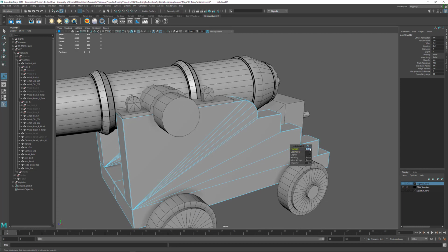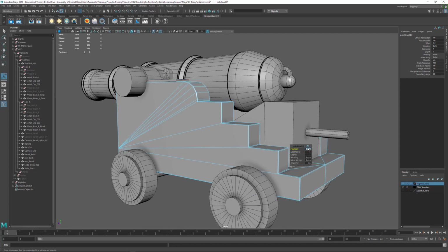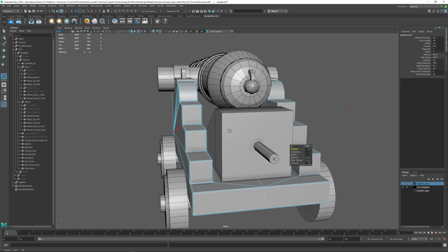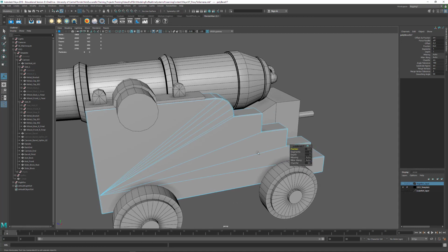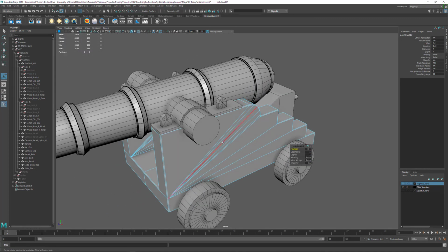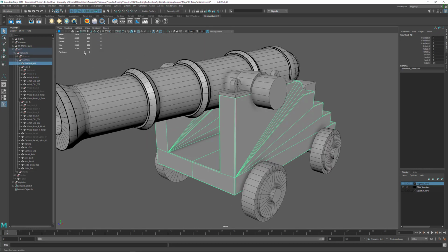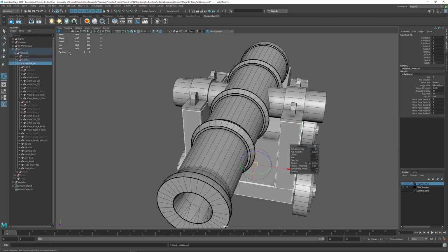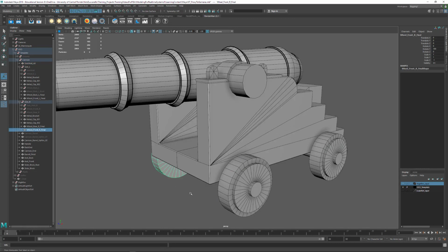If we want, we can pump that up to 0.25. I don't want to go too high with it. Like say we go 0.5, that's maybe just a little bit too thick. So maybe 0.4 is about as high as I would go with this. But if you can afford it, the beveling has a pretty nice effect to it. So I'll hit F8, I'll hit Alt-Shift-D to delete history. So that's in green because it's in object mode. Now we'll go back to mesh and we'll mirror across. And so now let's do that again. Mesh, mirror, and now we've got our beveling going across everywhere.